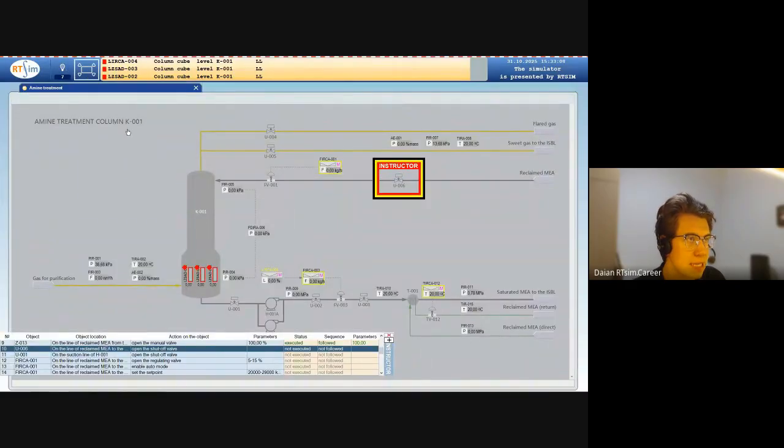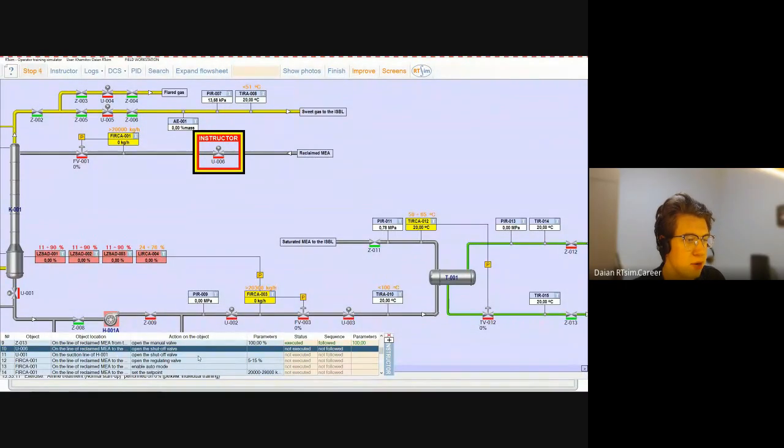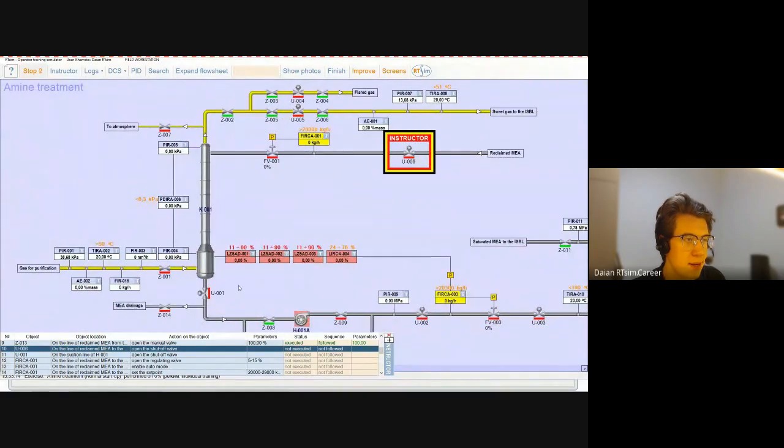And let's see which manual valves haven't opened. The raw material gas purification manual valve remained closed because it's too early to feed gas for cleaning while monoethanolamine has not yet been fed into the column. The gas will simply exit the pipe and continue along the process line unpurified. So we will start the regenerated monoethanolamine first.